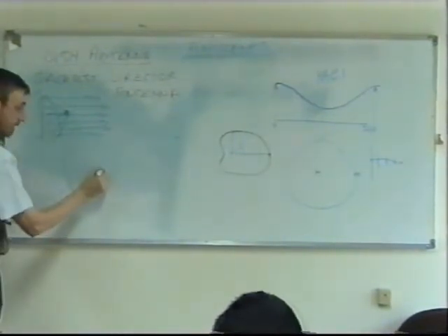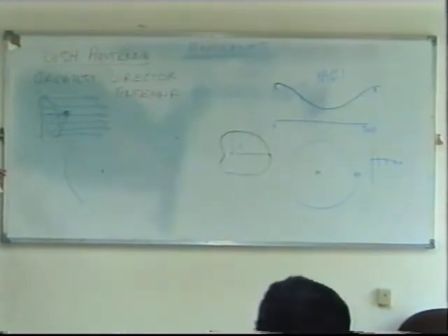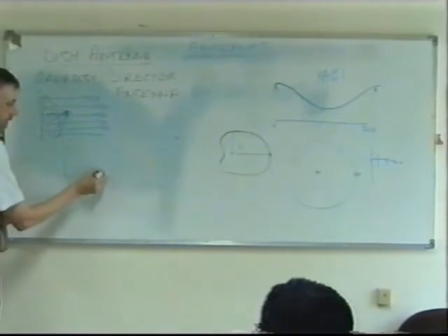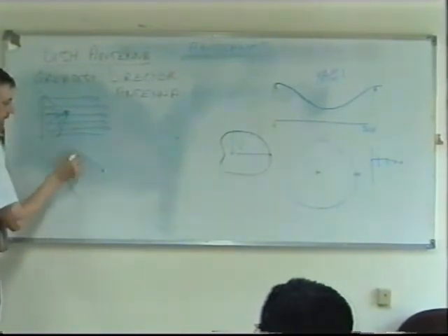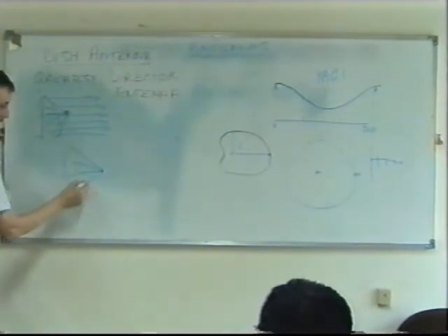That's where we would place the actual antenna. It's like optical physics, very similar. Because, don't forget, the higher the frequencies we're using, the closer to light waves we're getting. So we're going to start to treat our radio waves more like light waves. And this is where the antenna is, and then it radiates this way towards the reflector.